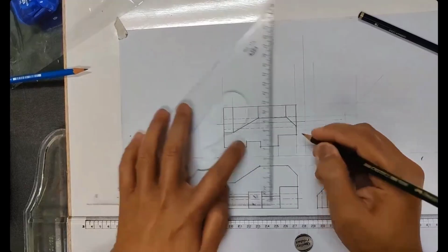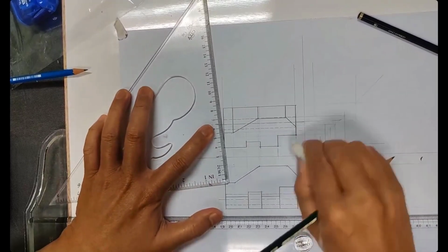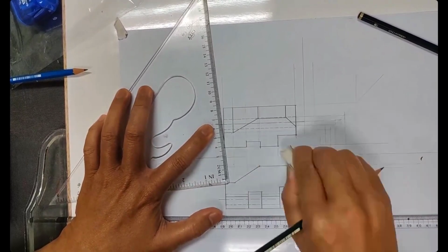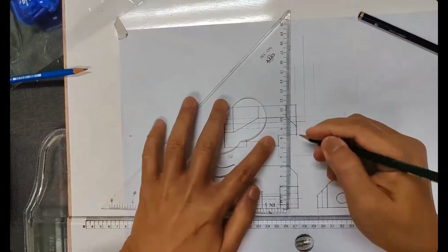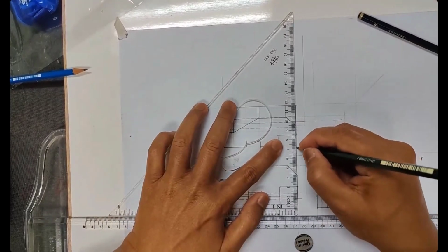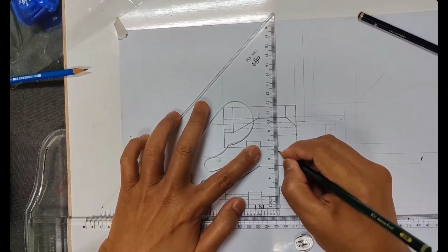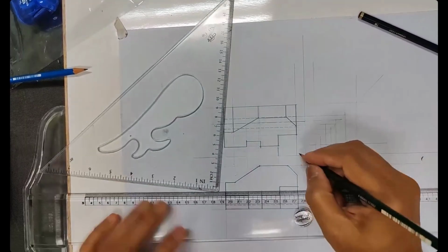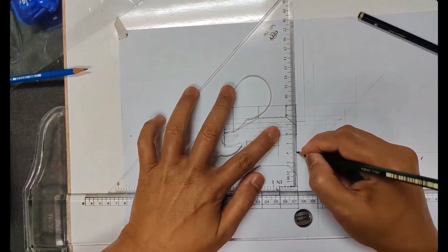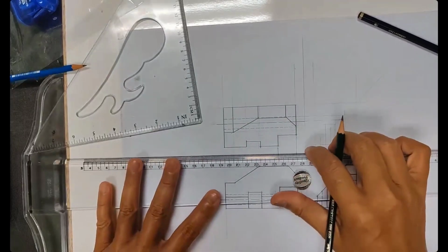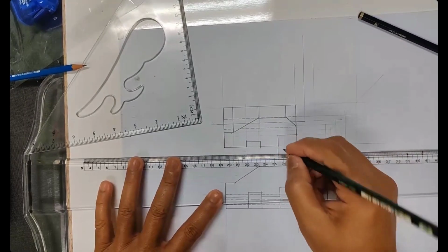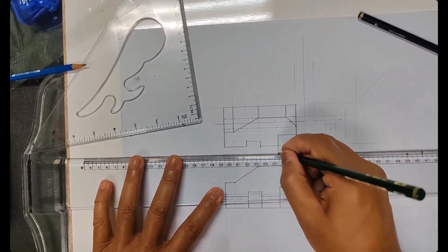I have 2 extension lines. You can erase a little bit if the extension line that you created is too much. I want to show extension line of the dimension. So this will be my extension line of my dimension. I'm not touching the corner, so about this level. It's about 2 letter height. This is my extension line, so it's about here. So the first level about here, about 2 letter height. So this will be my dimension line.